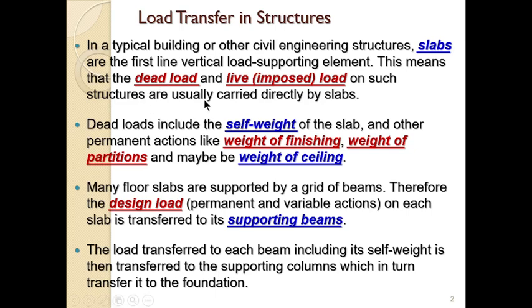And the dead load includes things like the self-weight of the slab and other permanent actions, which include the weight of finishing, the weight of the partitions, and maybe the weight of ceiling, assuming the ceiling is attached to this floor slab.